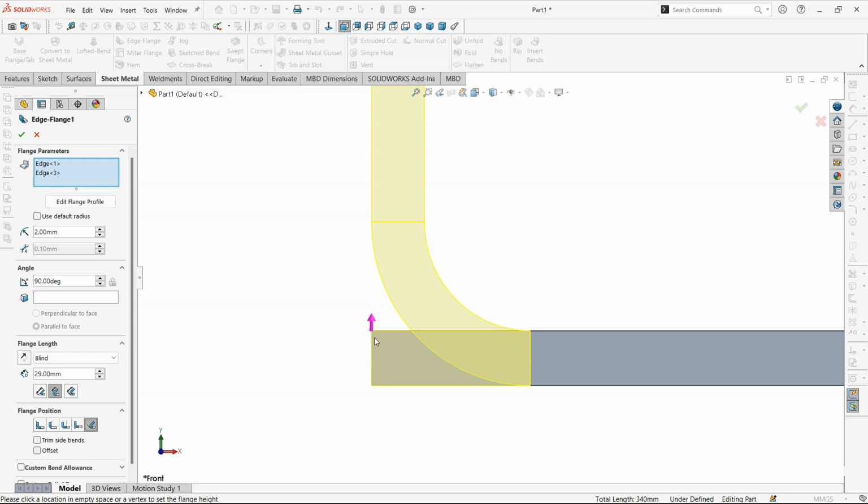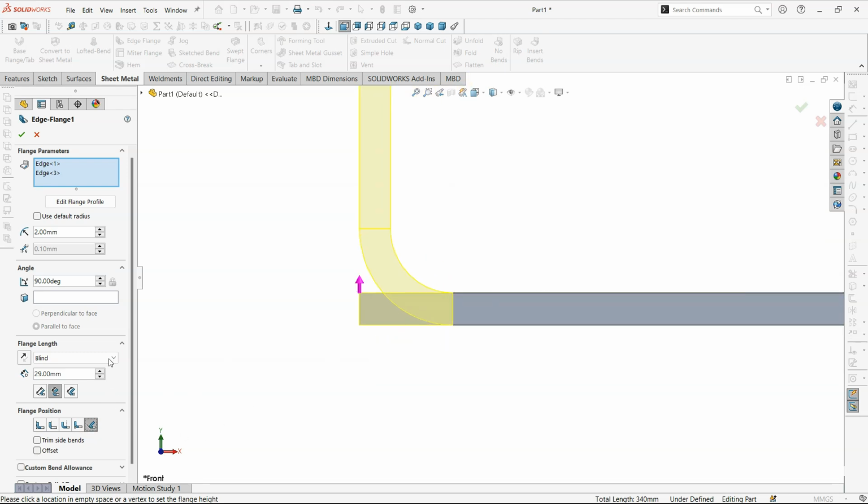And lastly, this means we can give it angles. If we change the angle, you see here currently the radius is also being changed. But if I select this point, the radius will be the same and only the upper portion is moving. But if I select this, you see the bend is also being increased. So that's the difference between them.